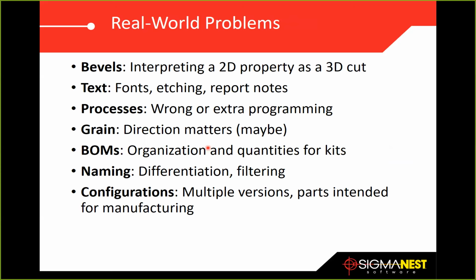Additionally, processes, this is talking about machine processes, that this contour should be treated with this tool or this process. Either that's mapped in correctly because the laser, plasma, oxy, water jet, whoever the machine programmer is, didn't know about that request from the CAD model. It's just geometry, so the programmer just does what they do best and adds process information.